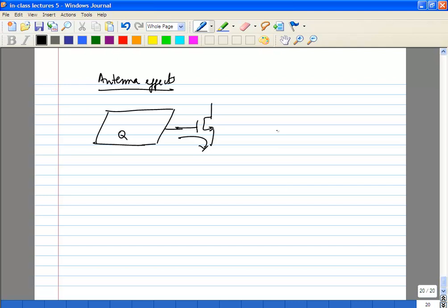If you want to prevent this, one common way is to add a reverse bias diode, very small. You have rules for that. For a given amount of area, you need to have a certain amount of reverse bias diode connected to your long lines. Or what you could do is split this up such that it goes up to one metal layer and then comes back down. You can add vias to break the connections to your gate. You can do techniques like that.